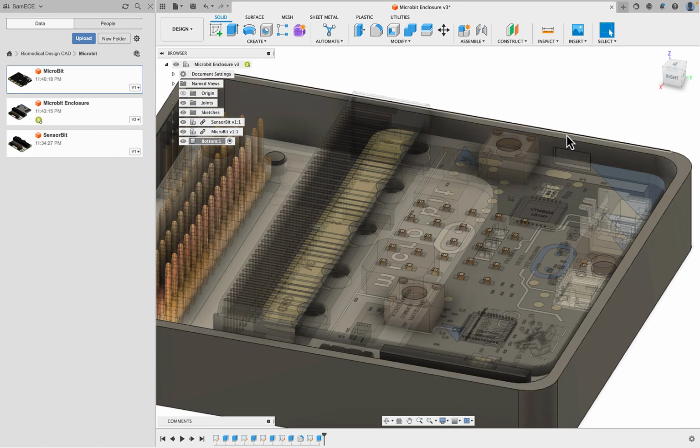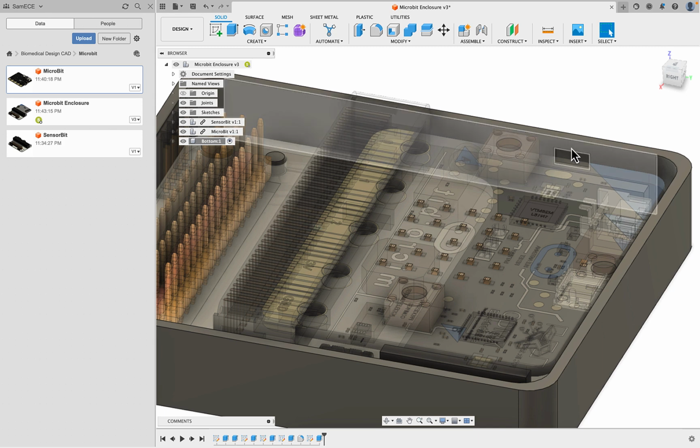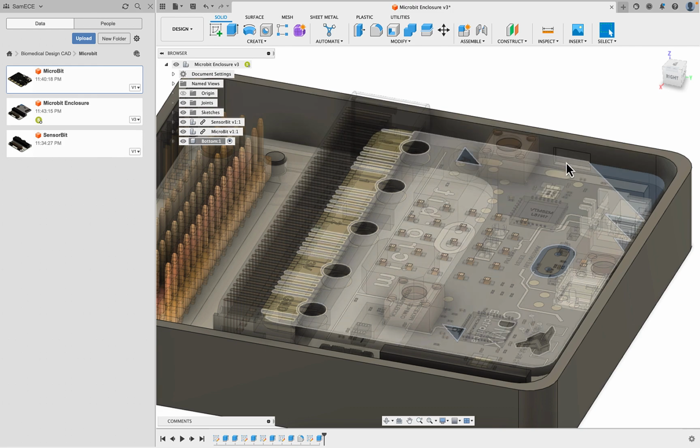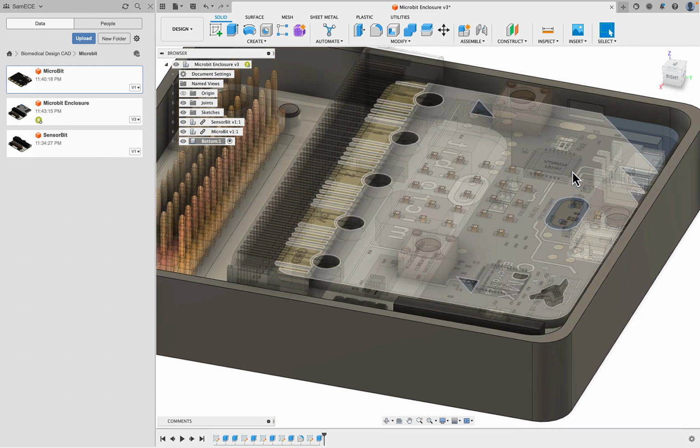So if we do a sort of tab here with a little bit of extrusion down here and create the right amount of thickness of the tab, it'll just flex and snap into place down here. And again, trial and error. If we make it too tight, it'll break off, and if we make it too loose, the lid will come off. So that's a thing. I'll actually print a few just to find out what I'd like as a force. So this one I would like to mirror.